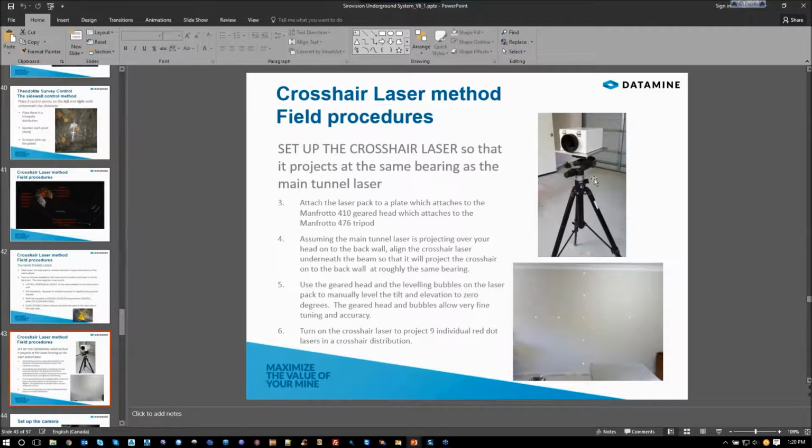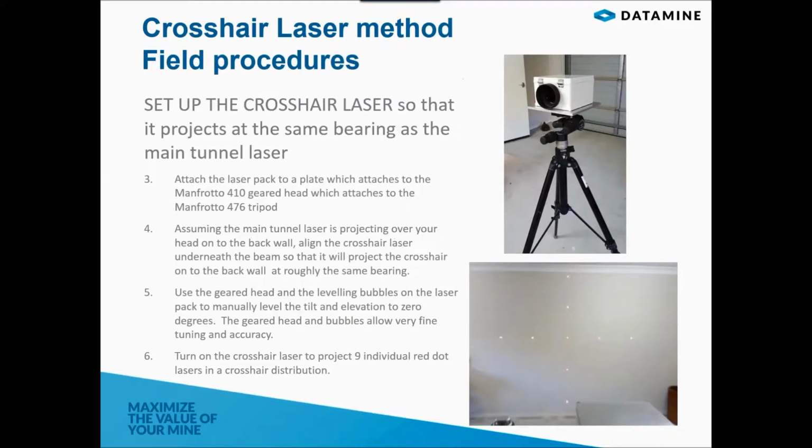So this is the tool that was used for the surveying. It's just this box and it sets out a series of points. You know your position of your tripod with your survey points. Use this, and then it'll georeference the face without actually having to go to the face to mark up survey points.